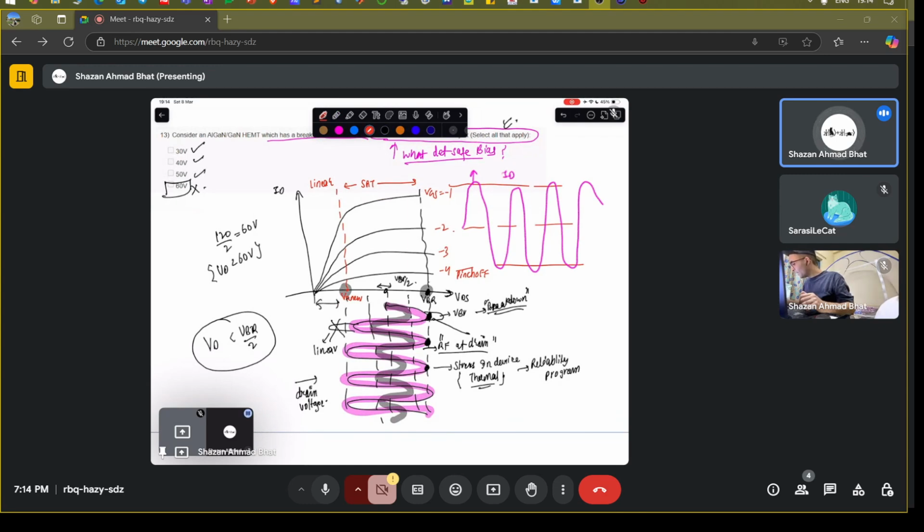If it overshoots this peak, it will go into the maximum drain current value, a very huge current value, and if it goes below this value, it will go into the pinch-off region. So there will be clipping of those peaks. That's why you want the current also to be in between. That's what gives you the load line, which may look something like this. With the load line, you want to bias your device around this point.